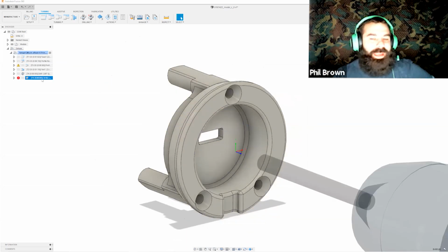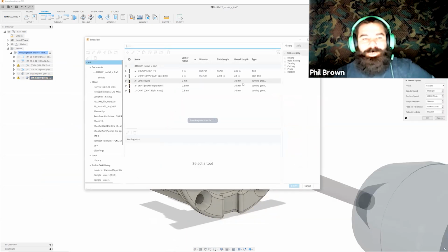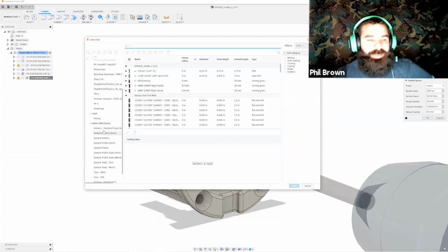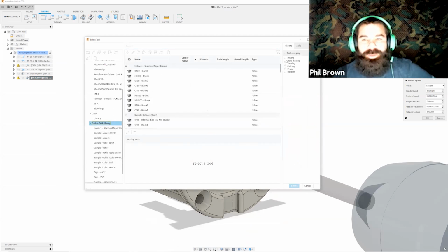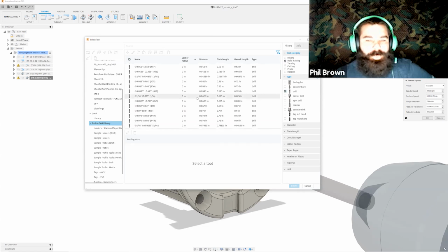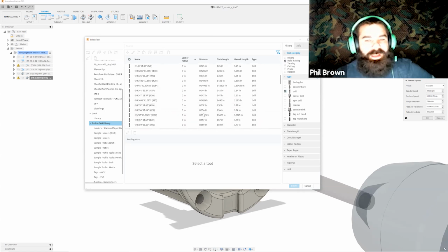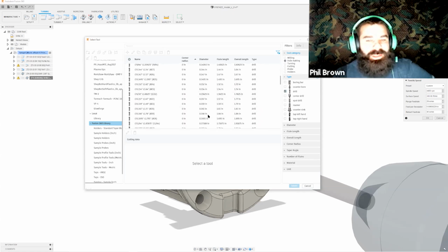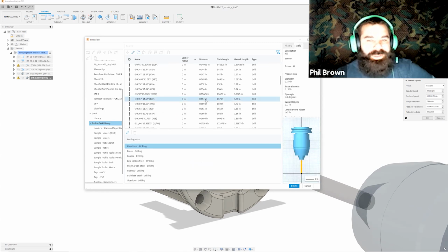Awesome. So that being said, I do have another template that's kind of a neat system here. So we know that's a 156 hole. Let me go ahead and pull in a drill bit that's 156. I do have a template, and what this template actually allows me to do is to auto find holes based on the drill size. So if my drill size is within a certain tolerance of my actual hole size, it will auto define those holes for me.